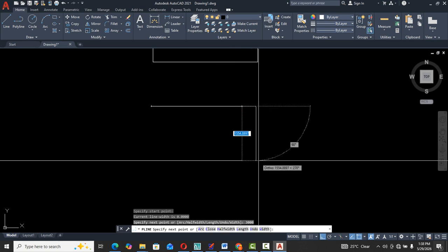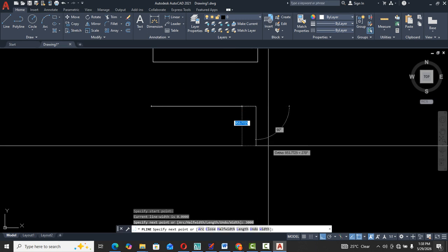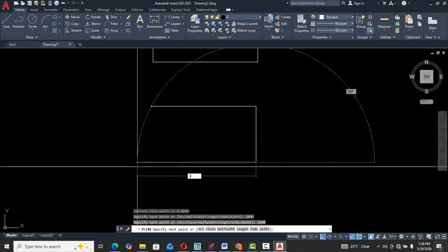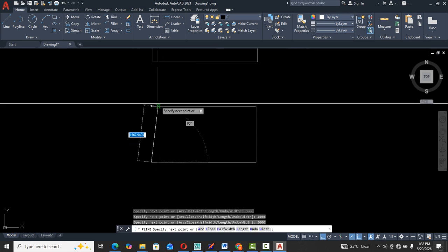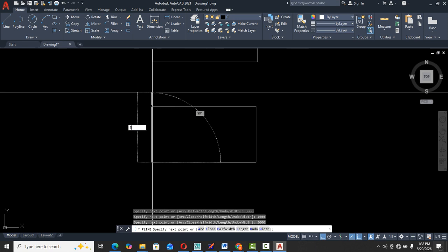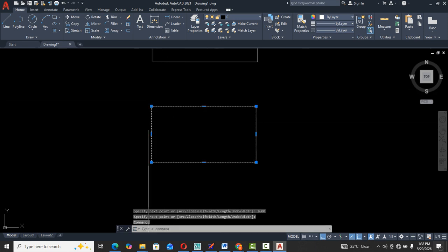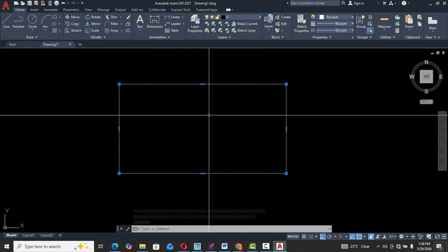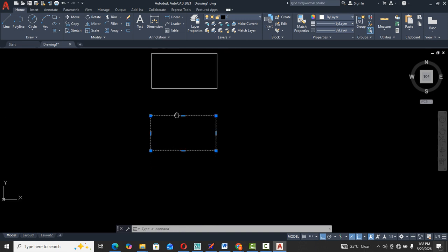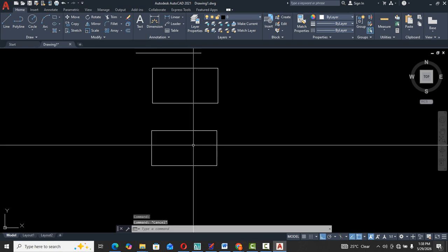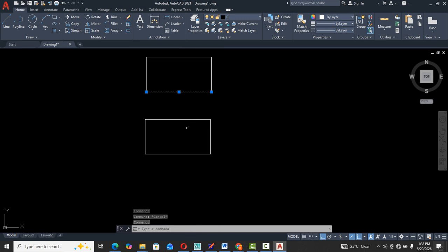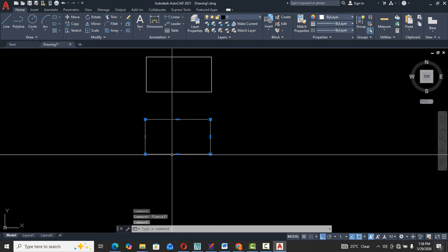But when we go to polyline, the difference is that polyline creates a 2D polyline. A 2D polyline is a connected sequence of segments created as a single planar object. You can create straight line segments, arc segments, or a combination of the two. In other words, we have a polyline of 1, 2, 3, 4, 5, 6. If you create a polyline, it becomes a single element, 1, 2, 3, 4 as a whole. You cannot select segment 1, 2 separately if you use polylines.